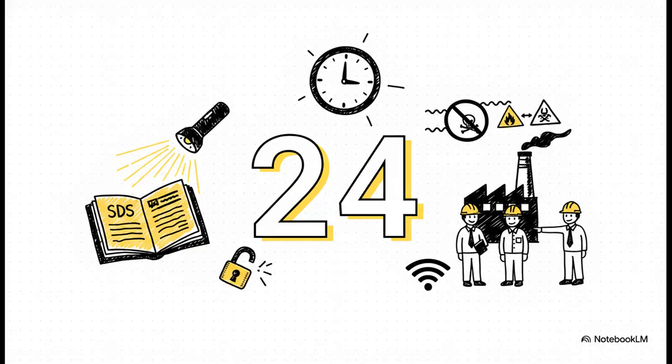But here's the thing. A document is completely useless if you can't read it when an emergency strikes at, say, 2 a.m. Your plant's SDS binders, whether they're physical binders or electronic databases, must be accessible 24/7. They have to be available to all employees across all active shifts. They cannot be locked away in a manager's office where you can't reach them during a night shift chemical spill. That 24/7 access, it's a non-negotiable federal mandate.